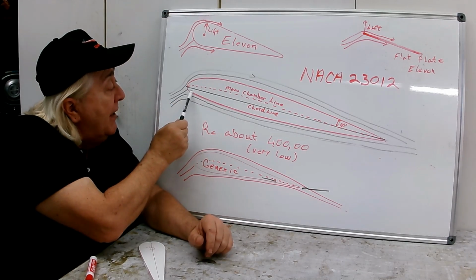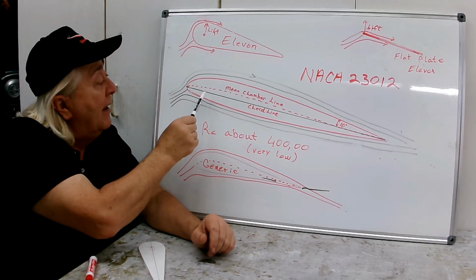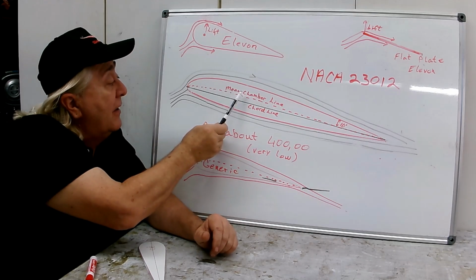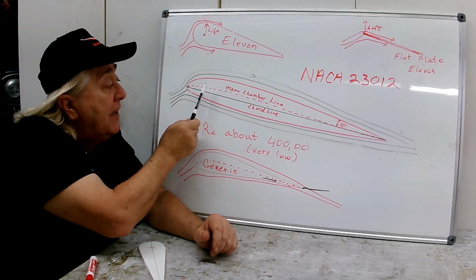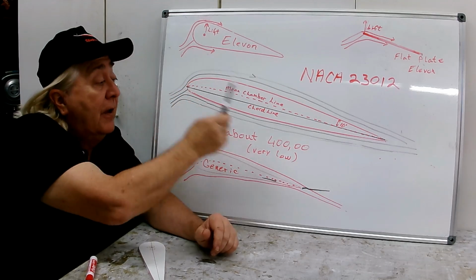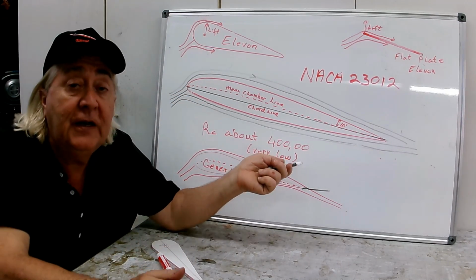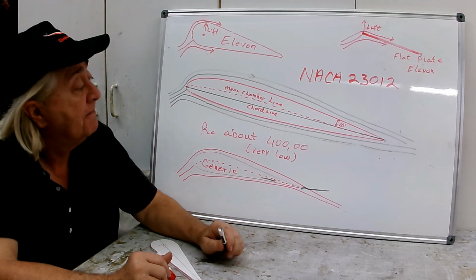I call it a dip. It's kind of flat here, and then it goes back down lower, and then it curves. And that makes the airfoil what we call front-loaded. The center of lift is further forward on these airfoils than on most airfoils. And that helps hold the nose of the airfoil up, and the reflex helps push the nose up, and that gives this airfoil a nice neutral pitching moment curve, which we love for flying wings.